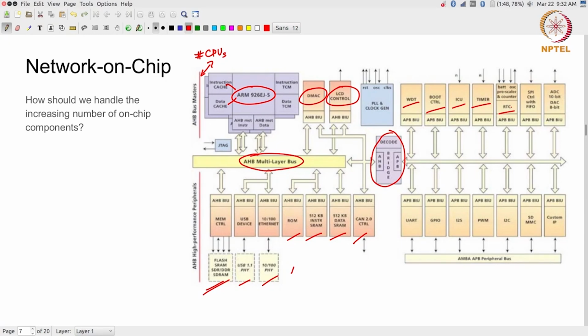So the point is, in principle you can start thinking of any of these things as potentially peripherals that are all talking to a single bus. Even if I have a many core system, I can think of it as having hundreds of bus masters talking on the same bus. Obviously, if I try having one bus as the bottleneck between all of them, that becomes a major problem. I can't afford that. But more importantly, the question is, how do I even build such a system?